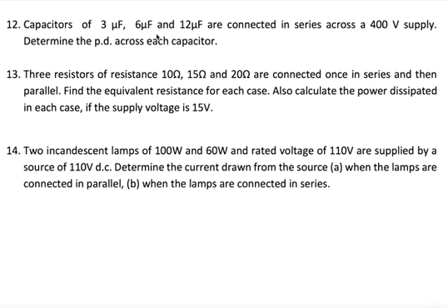Capacitors of 3 microfarad, 6 microfarad, 12 microfarad are connected in series across a 400 volt supply. Determine the potential difference across each capacitor. So this is the situation here. Three capacitors are connected across a 400 volt supply.